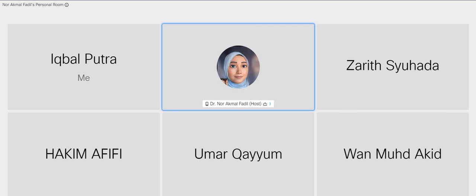For example, whatever I've explained earlier, if the hardness meets the requirement, for example, the highest hardness need to be achieved by quenching process, and only the quenching process can give the value of that particular hardness, and the structure experiences compression loads, there's no issue on the accidental or impact load, the quenching process is sufficient.